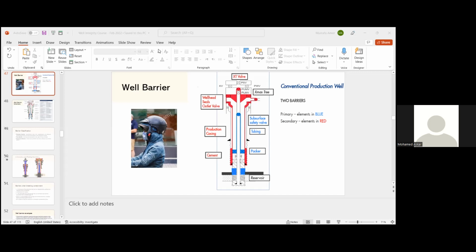So the least action to be made for this situation is just to monitor the pressure at periodic intervals and bleed the pressure if it gets above the upper limit, or just keep it above the lower limit, so as not to induce more fluids. If it's just saline water, you want to keep an eye on it and keep your pressures contained and safe between the two casings, so as not to impose high pressure that affects your facilities. Just some notes you can consider in your decision about monitoring and assessing the risk for these wells.